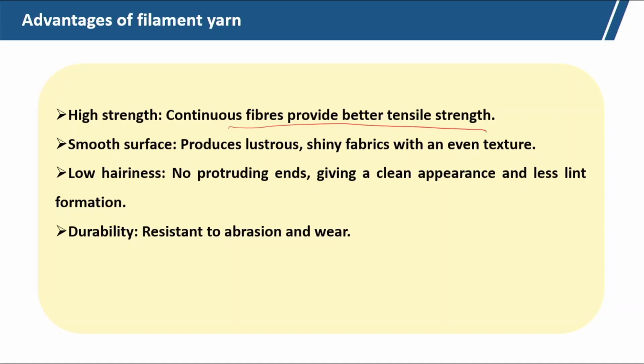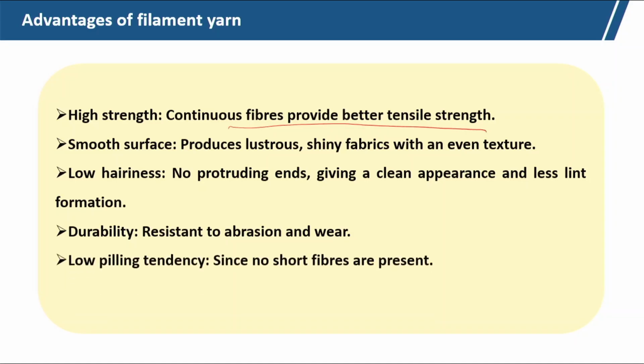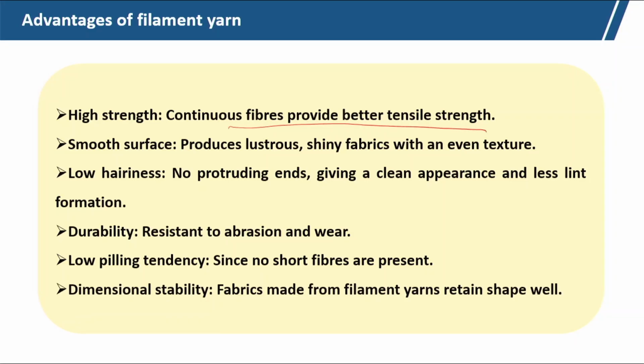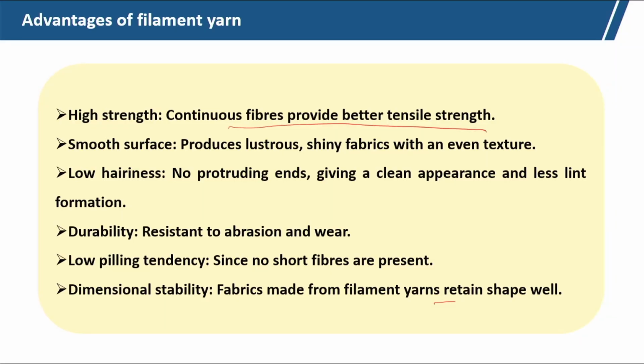Durability is high because of resistance to abrasion and wear, and low peeling tendency. The dimensional stability of fabric made from filament yarn is good, it retains shape well because it does not get swelled. For staple fiber yarn, due to the pores, when water penetrates inside the pores, there is a chance of swelling, but here there are no such pores available. So, swelling is not there.